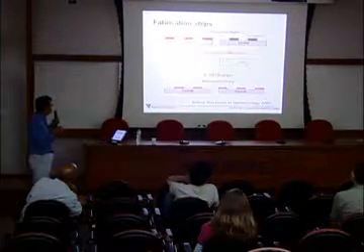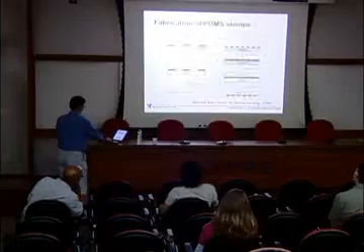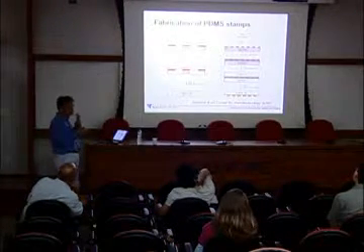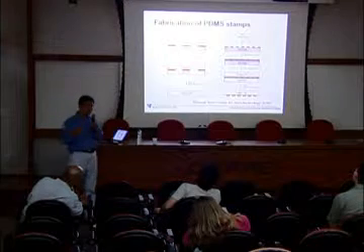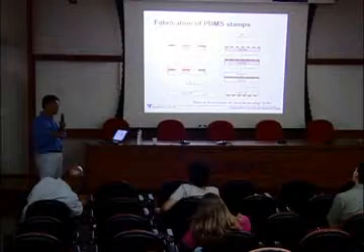And then we can pour the polymer. We supply the polymer onto that. This polymer will be cured on the structure. Then after that, the polymer structure can be made. Then this polymer structure will be dipped in a solution having an ink. Ink means it can be a lot of molecules or solutions containing some target molecules. And then we can just stamp on the surface, then that's it.